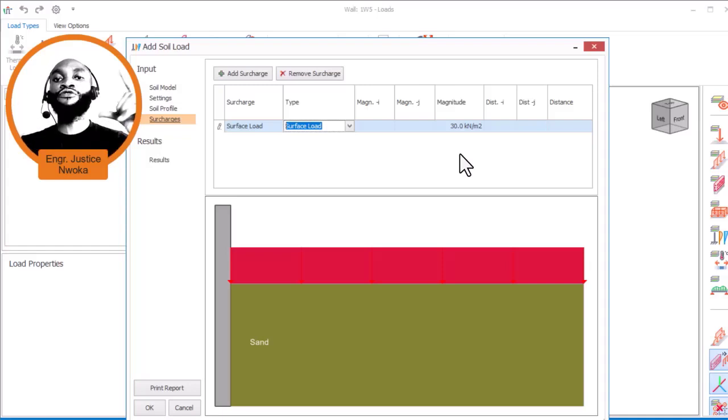So you can pick any load from there depending on the activities that occur around the perimeters of your basement, retaining wall or structure. Knowing that 10 is the minimum and 20 is the maximum, you can choose to exceed if you know that much activity will occur there.